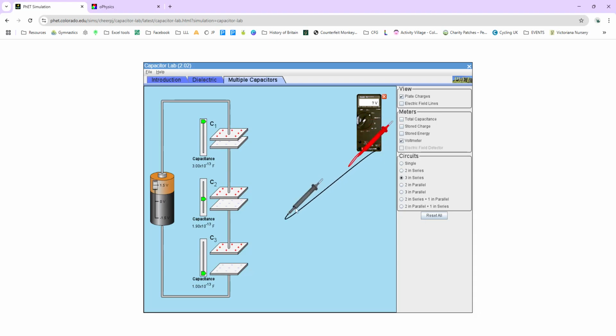If we have a look at the voltages on the low capacitance plate, that is 0.8 volts approximately. We have a look at the next one, that is even smaller, and the smallest voltage is on the highest capacitance capacitor. And you'll notice if you rewind and add these numbers together that they add up to equal the voltage of the power supply. Capacitors in series behave very similarly to resistors in parallel.